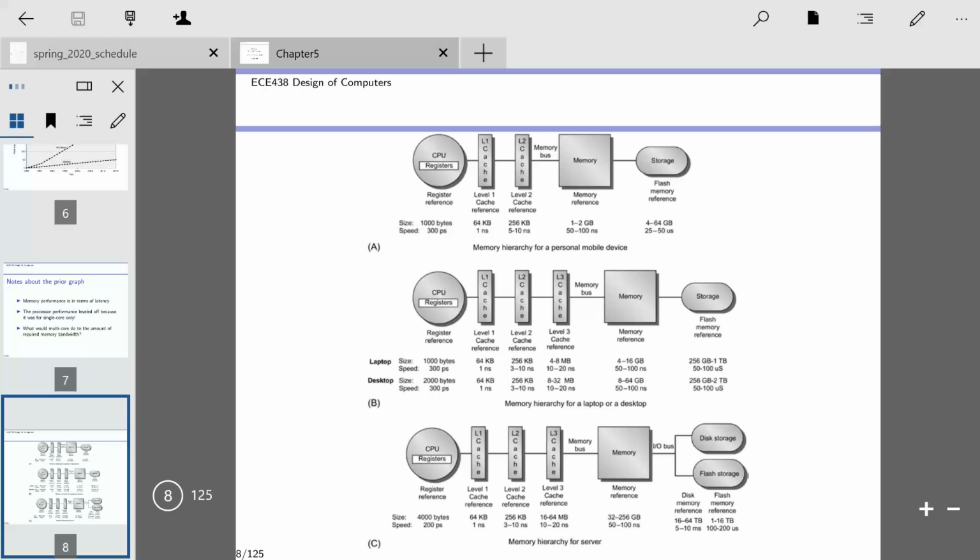And the same mistakes were made with the Pentium, as they said, well, they took two 486 pipelines and put them together so they could fetch multiple instructions, and they implemented superscalar. Well, that is superscalar, taking those two pipelines and allowing the processor to now fetch multiple instructions per cycle. So anyway, I wanted to point that out.